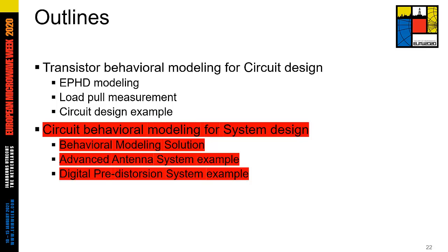We have seen how the EPHD model extracted from load pull measurement allows us to design power amplifiers. We are going to see now how PA measurement or PA simulation allows us to extract behavior models to design systems, through two application examples, which are advanced antenna systems and linearization systems.